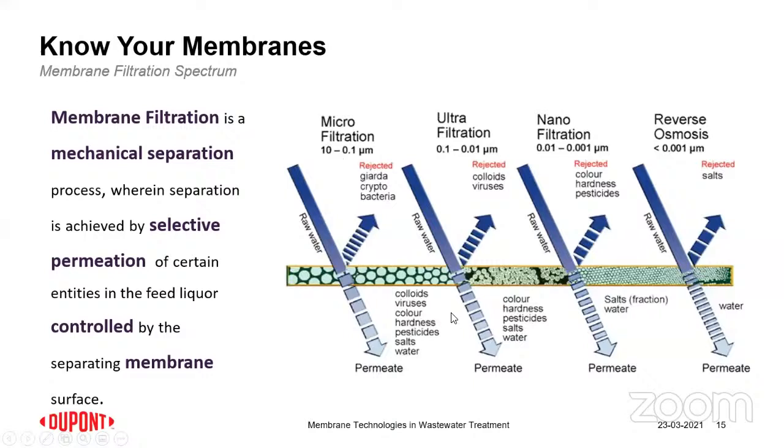So microfiltration typically removes almost all suspended particles, but has trouble with some of the colloids. Sorry, it rejects bacteria and bacteria-like particles, but allows some colloids, some suspended and of course dissolved particles, and some viruses.